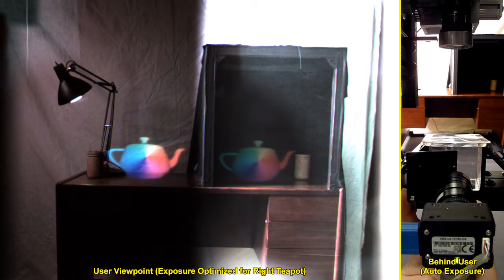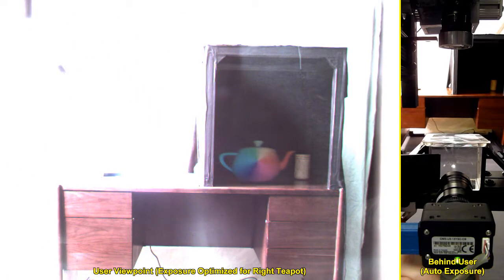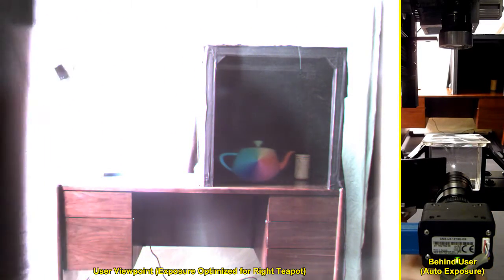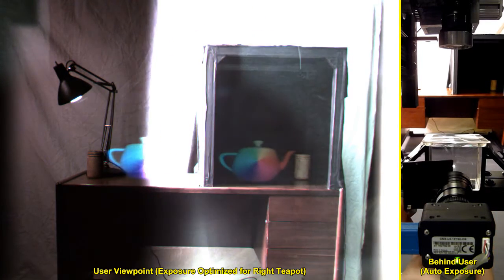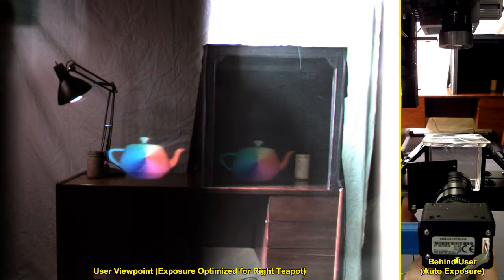This range exceeds that of the user camera, so we demonstrate the range by moving a neutral density filter in between the display and the camera. When the filter is present over the left teapot, note that both teapots are fully detailed. This filter cuts almost 98% or 34 dB of the light.